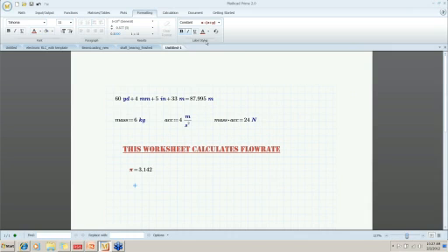You can apply label styles to these items here: variables, constants, units, built-in functions, system words, and keywords. That makes it easy to distinguish between variables and constants and units, because sometimes people might have a variable called m, but m is also a built-in unit for one meter. So if you really want to clarify what's going on and minimize confusion, this is a very compelling way to do that.